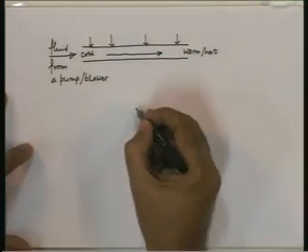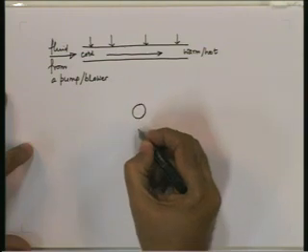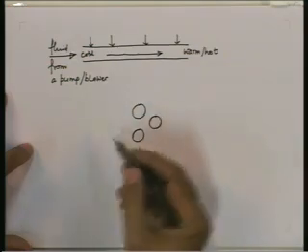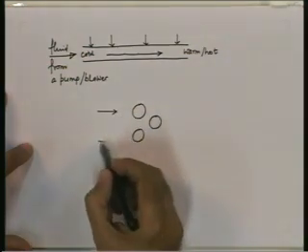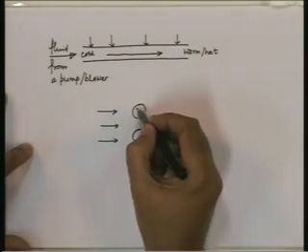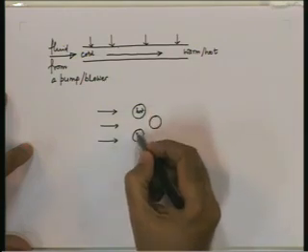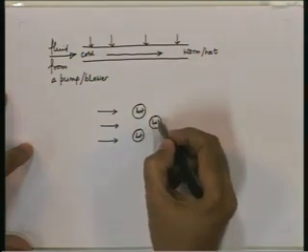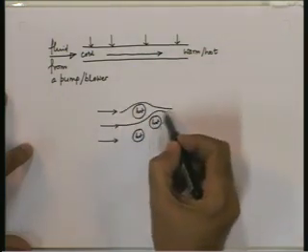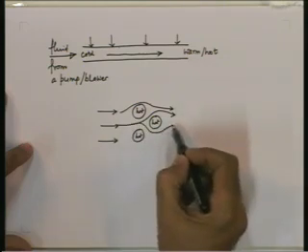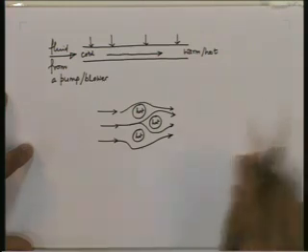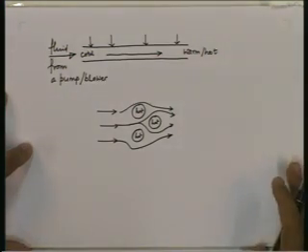Another situation is one in which you have a number of tubes, as in a heat exchanger. I am showing a cross section, and fluid is forced to flow over them. Tubes contain hot fluid, so their surface is at a higher temperature than that of the fluid. The fluid passes over and through the tube banks, becoming warmer. This is another forced convection situation.